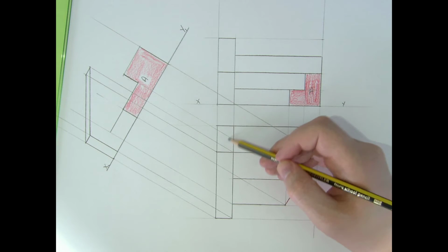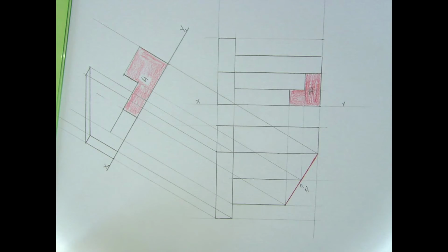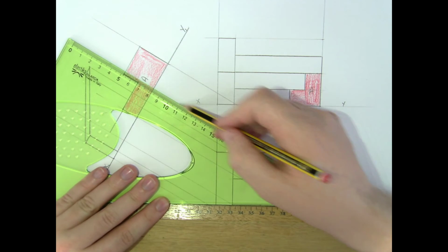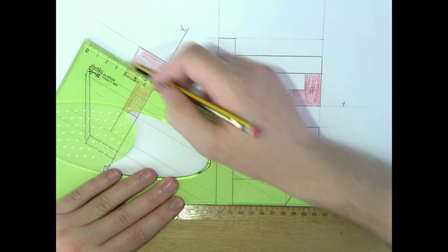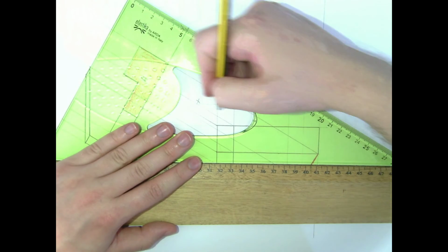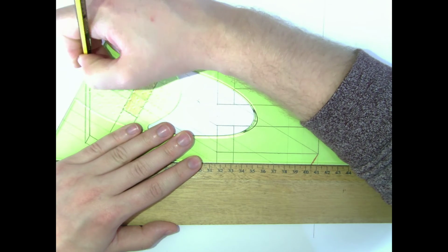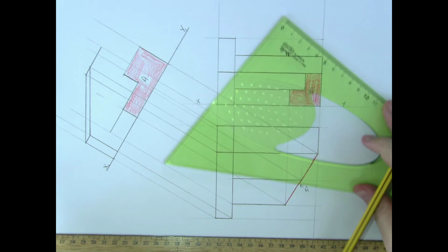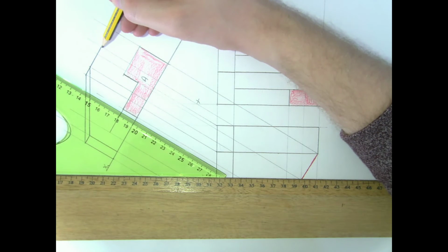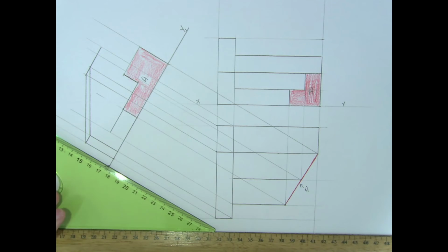Final part of this wall is this block part of it, that top part of it up there, where it levels off, where it becomes flat. So we're going to find both of those points and project them up also. Their height is up at the same, so they are also up a height of 60. Now I'm not going to draw in this part of it just yet, as we need to find the other steps before we can see where they disappear.